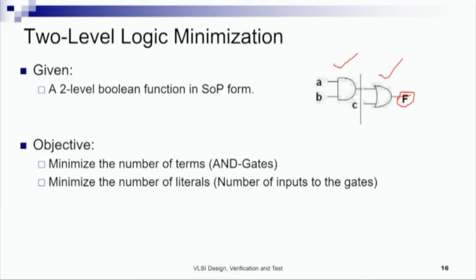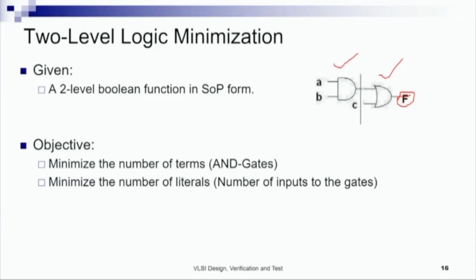Moreover, although the delay, which is primarily represented by the number of levels, is lowest in two-level logic expressions, the area consumed is many times very huge, where the area of the corresponding structural representation is denoted by the number of literals in the Boolean logic expression.